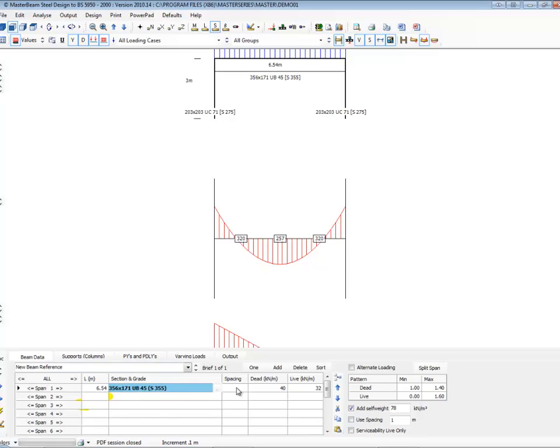I'm going to turn around and say that I have beams at a spacing of 4 meters. So therefore, I'm just going to multiply up everything by that and say 5 live load. In fact, I'll leave that back and I'll put it in here. So I'll use this spacing globally, not just for these simple dead and live loads. I'll use this in here and we'll say it's 4 meters apart.